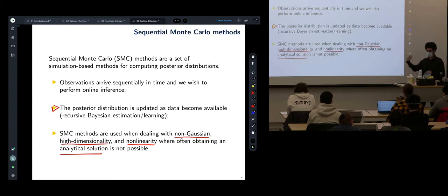If it's perceptual data, for example, cameras, LiDAR, radar, they come at a lower frequency, but they have higher bandwidth. So the spatial sensors, a point cloud from LiDAR can have 100,000 points, or a stereo camera can give you 300,000 points. And they come at maybe 10 hertz, 30 hertz, maybe 60 hertz, but it would never be kilohertz at this point, at least.